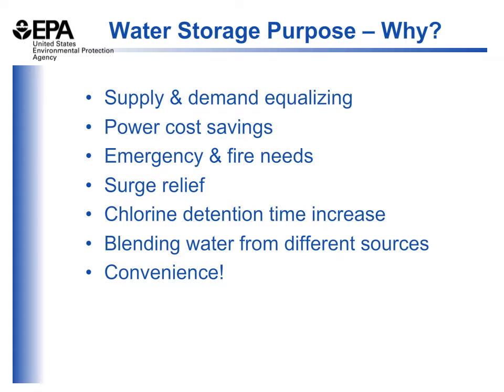A question: why do we want to store water? Well, for one thing, your supply and demand are not equal at all times. If everyone's using water at the same time, you're going to see a large spike in the water demand. For example, if you have an industrial client that requires a lot of water at a certain time of day, it may be more than you can provide from your well or your surface water source or treatment plant. So having a storage tank helps you equalize your supply to your demand.